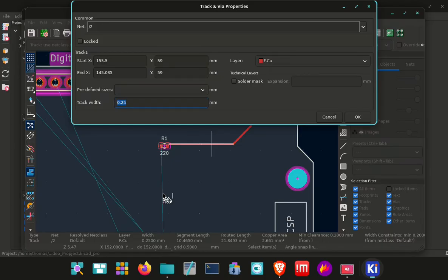If you were putting big components on and there isn't enough room between the Arduino and the board, then you want them on this side and the tracks on the back. But you may want this side to be flush, so you'll put your tracks on this side and the components on the back.